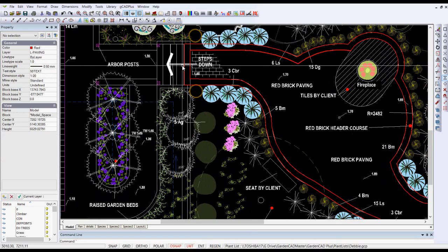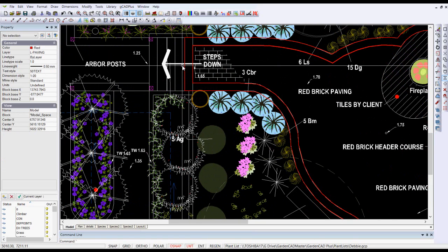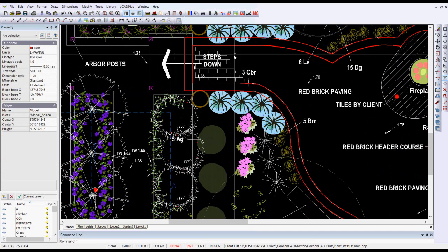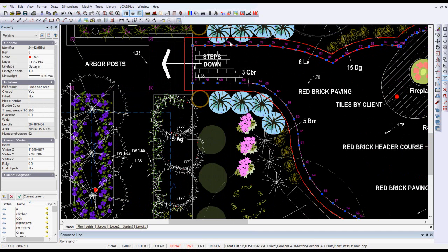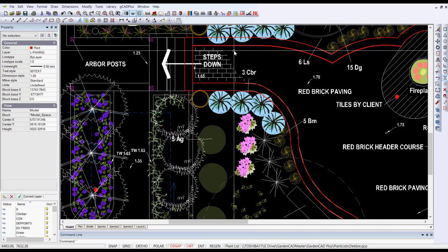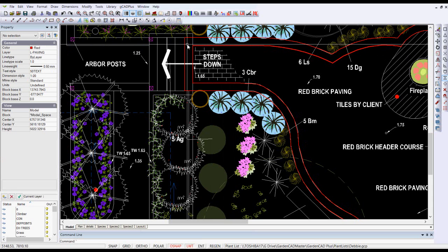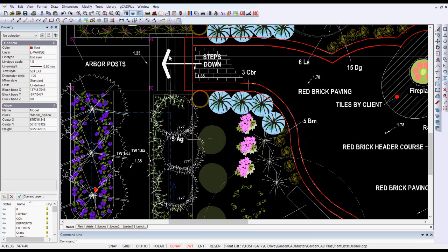What I want to show here is that a polyline can be edited very easily, and it's important to master that technique. The offset was quick and easy. We just selected this line here and offset 230 millimeters in this instance. But the offset took the outer polyline down into an area that will be delineated by some rectangles for steps. So I want to edit that polyline.